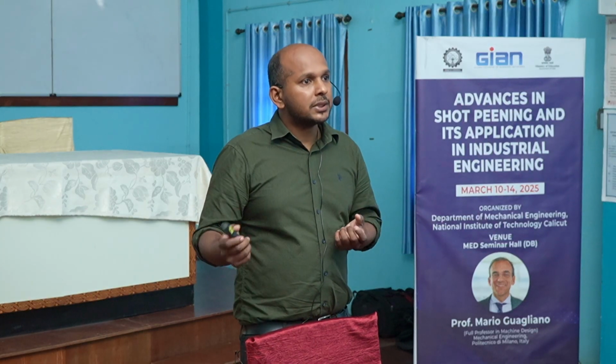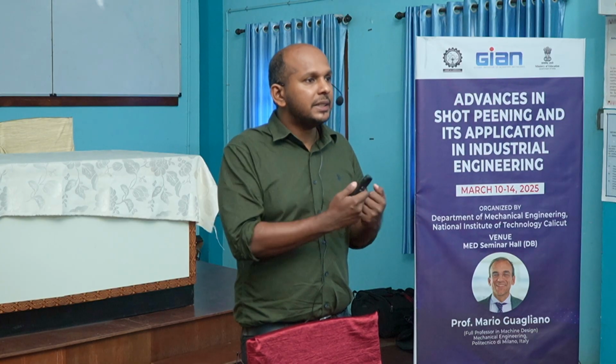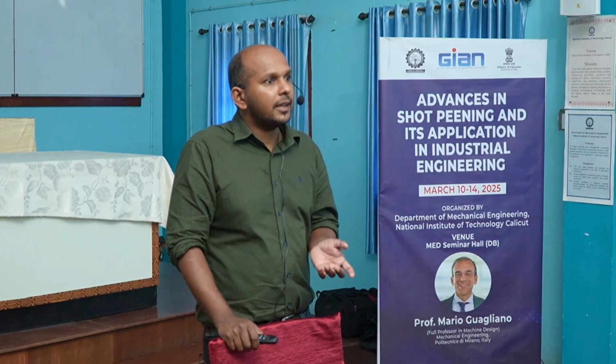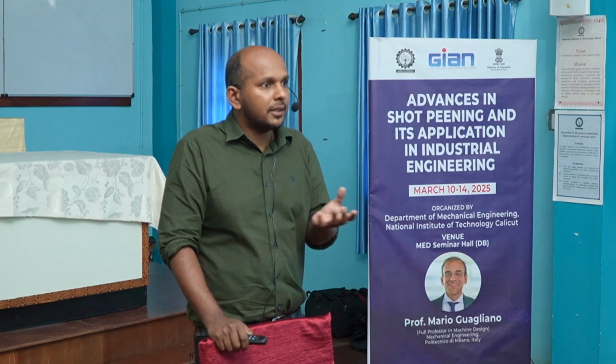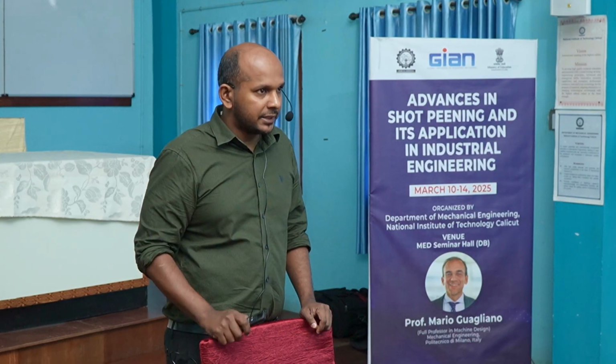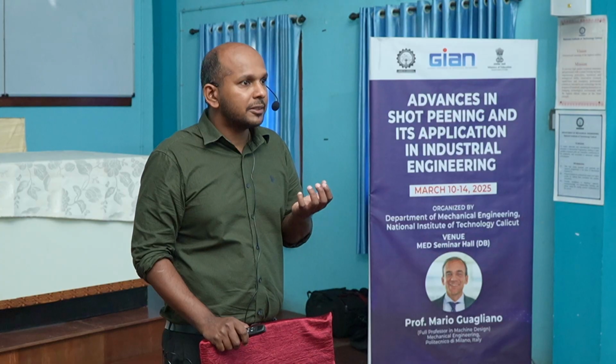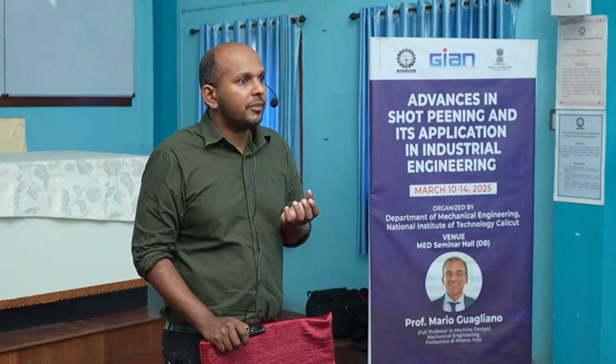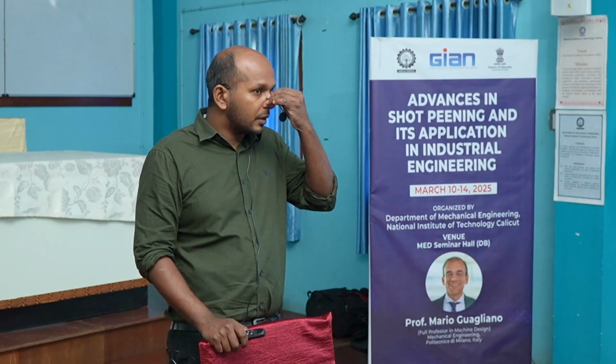In the second case, post shot peening worked because the surface was soft in nature and the particle was very hard. Once it is impinged, the pores become closed, and the hardness of the layer also improved. If it is too thin, as in the first sample, the peening completely damaged the coating surface. So it should have a minimum thickness and some favorable physical properties. But the more the thickness increases, the higher the possibility of brittle cracking on the coating.